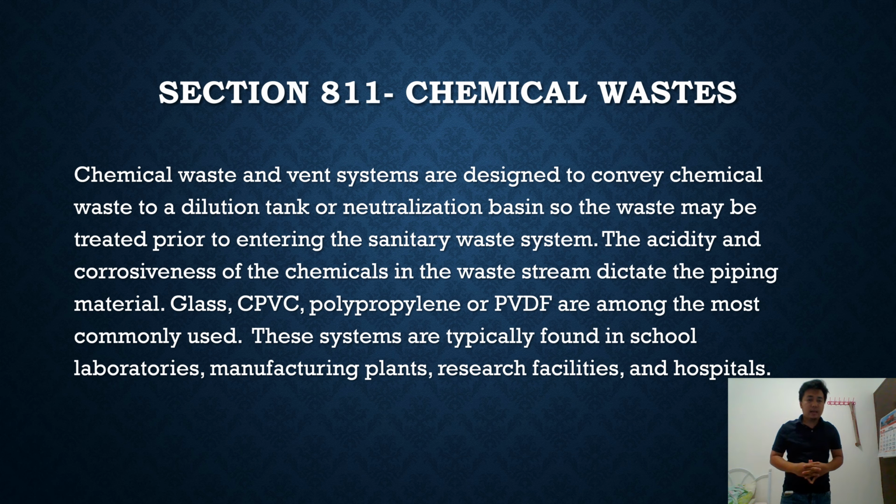The acidity and corrosiveness of the chemical in the waste stream dictate the piping material; glass, CPVC, polypropylene, or PVDF are among the most commonly used. These systems are typically found in school laboratories, manufacturing plants, research facilities, and hospitals.